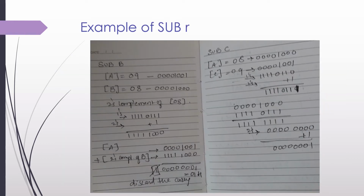You can see in this the example of subtract R, that is SUBB. A is equal to 09 I have taken, B is equal to 08, so you are doing SUBB, that is 9 minus 8. So you can see accumulator 9 is 0000 1001, that is 09, and 08 is 0000 1000.